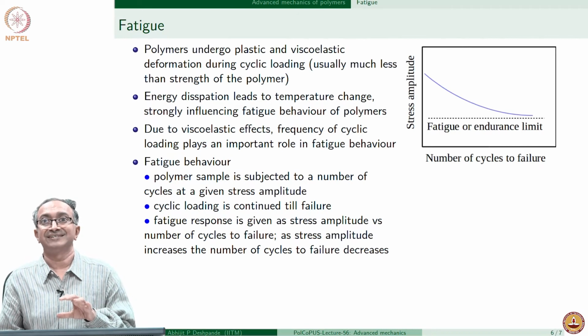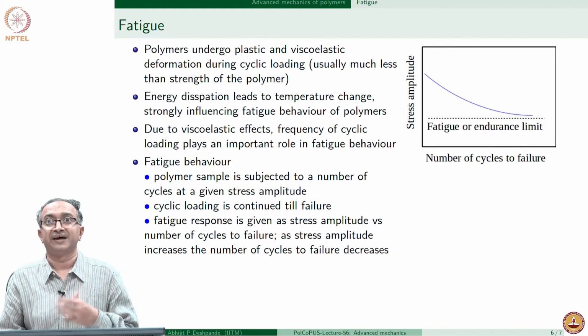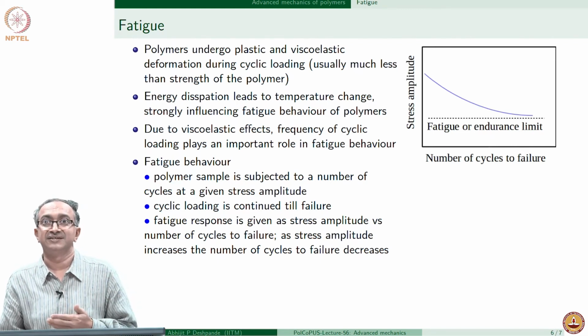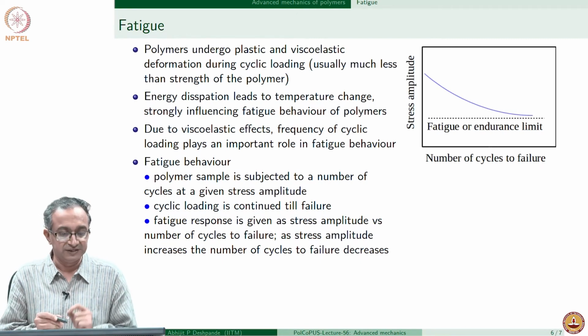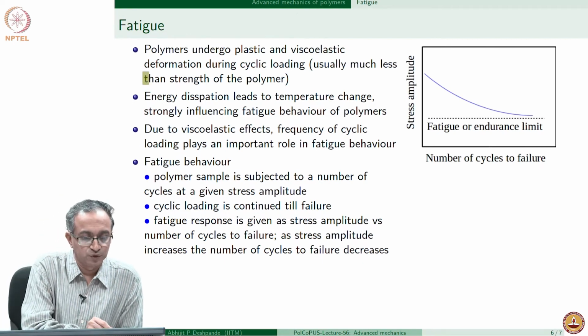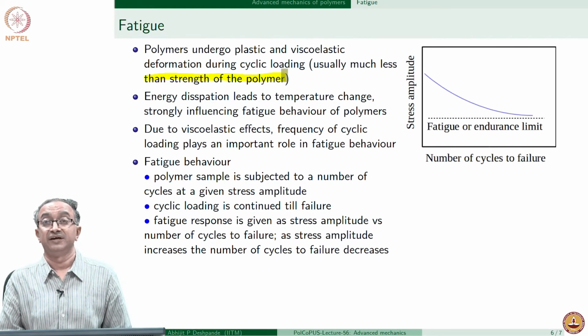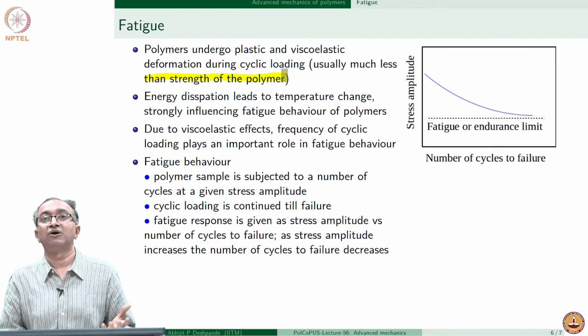Another important mechanism by which materials fail is related to what is called fatigue. And as we know, fatigue is basically getting tired in the usual English sense, and in case of mechanical response of fatigue, what is very crucial here is that we subject the material to loads which are much less compared to the tensile strength. It could be 20-30% of the tensile strength. So, technically the material should be able to withstand this kind of a load over very long periods of time.